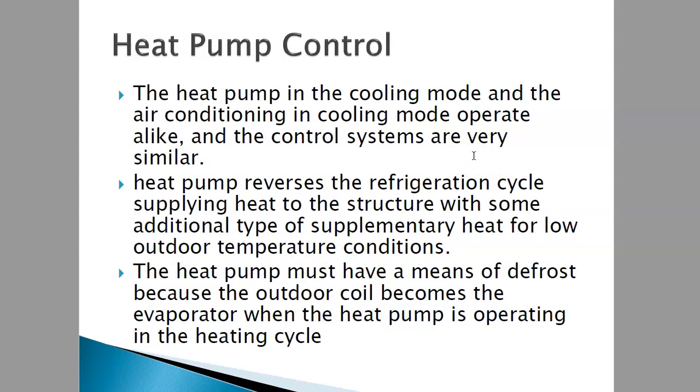Next we have heat pump control. A heat pump in cooling mode and an air conditioner in cooling mode operate alike, and the control systems are very similar. As you know, in Malaysia we have aircon, which is for cooling, but heat pumps are installed in four-season countries, where they can heat the house or cool the house. A heat pump is actually reverse refrigeration, supplying heat to the structure, sometimes with supplementary heat for low outdoor temperature conditions.